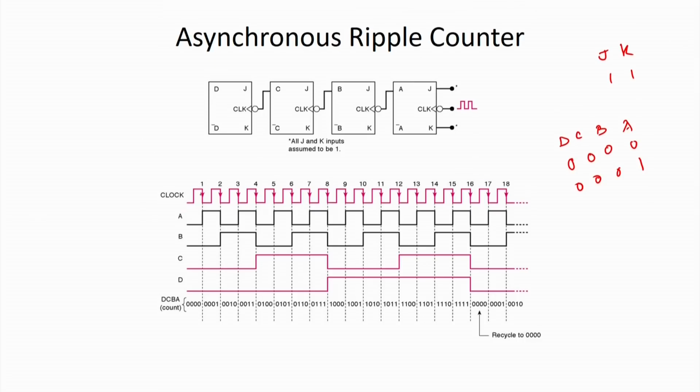You just see that when the clock arrives, A is going to change from 0 to 1, but B will remain 0. Now, whenever the next clock comes, again A is going to change, but now since this clock is available, B is going to change. So, now when this signal is coming over here, I am going to get 0 0 1 0. Similarly, when this comes as 1, it will remain as 1, so there is no change in the C block. It will remain 0, and when the next clock comes it is 1 1. So, we are going to have this type of behavior.